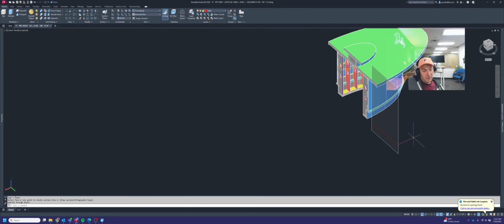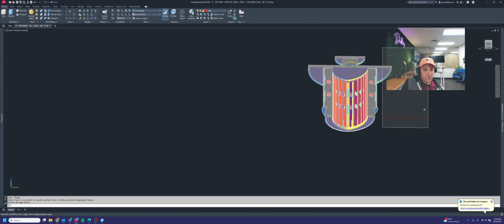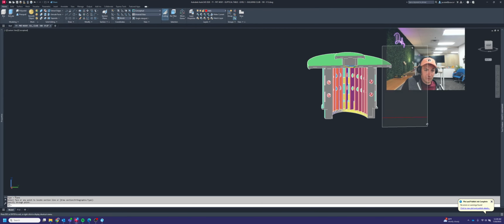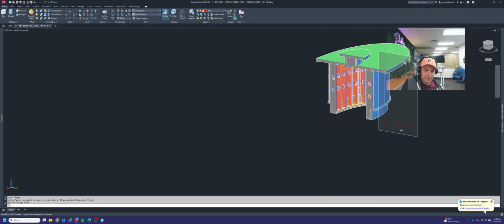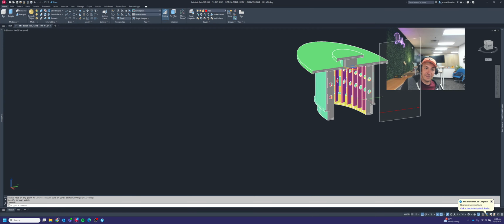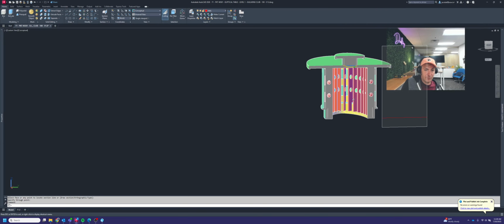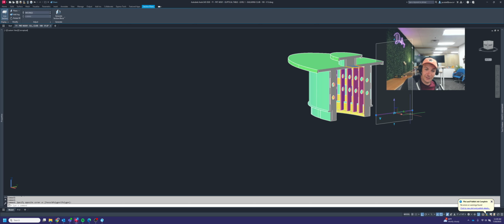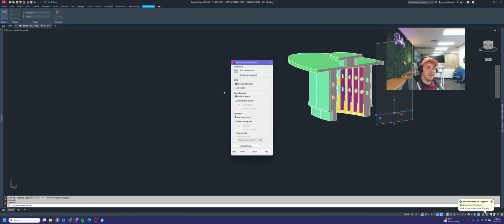All right. Now that I've got that, you can see slicing directly through the model, we're going to be able to see this half of it in that section cut, which is fine. That's actually what we want. So we're going to click on that section plane again, go up to generate section block, then generate section block again. Don't know why it's on there twice. So we'll go through there.